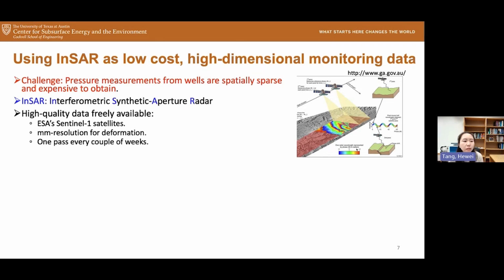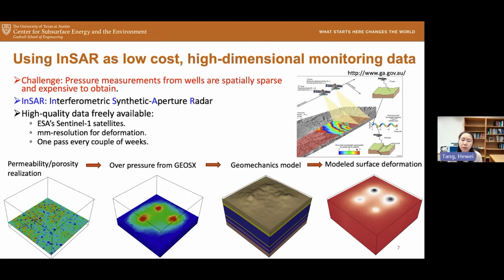So we are thinking whether we can use InSAR as low-cost, high-dimensional monitoring data. Here, InSAR stands for Interferometric Synthetic Aperture Radar, and it has high-quality data freely available, one pass every couple of weeks, and it can give millimeter resolution for deformation. So here we have some freely available high-dimensional data, and we also have the capability to simulate the surface deformation through coupled flow and mechanics.